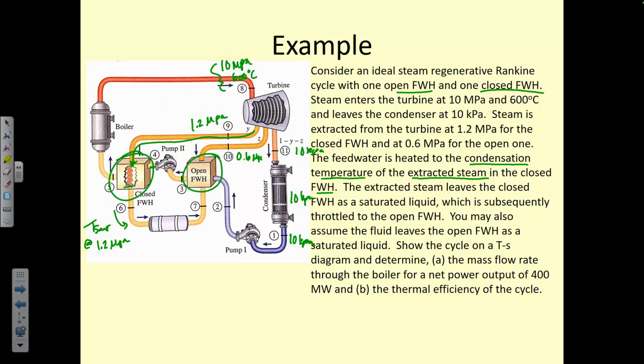So the feed water is heated to the condensation temperature of the extracted steam. What that means is that T5 is equal to T6. And T6 is going to be the saturation temperature at 1.2 megapascals.